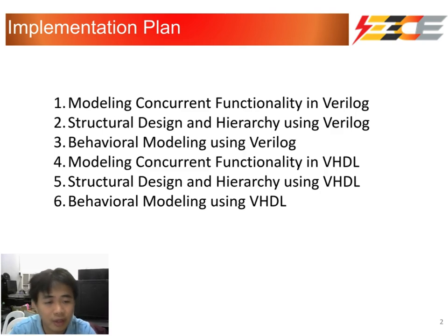Next, we implement the function. Each modeling style targets the same logic but has different uses. The dataflow uses compact Boolean assignments, the behavioral is procedural for clarity, while the structural is the explicit gate instantiation. We then create test benches to verify the behavior and record waveforms for visual confirmation.